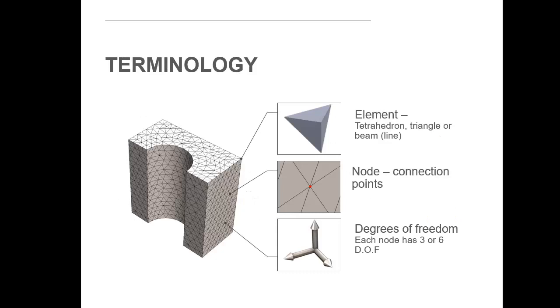For the CAD models that we are solving, we're mostly in 3D, and the domains of our equations are the 3D CAD models. So when we want to calculate the displacements of some component under load, it's the component we divide into finite elements and solve the differential equation for elasticity in that domain. So, the 3D model is divided into elements.